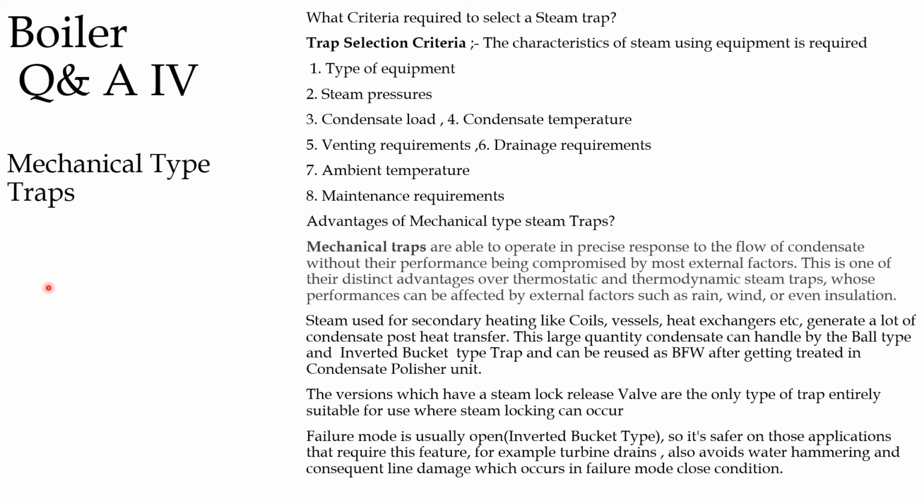Hope you understand the mechanical type of steam trap, float type, ball float type and inverted bucket type operation, advantages and disadvantages, and the main advantages over the thermostatic and thermodynamic traps. And where condensate collection is more and condensate load is more, a mechanical trap is advisable and suitable to select.